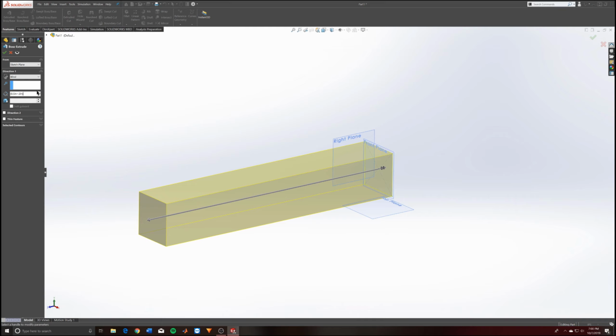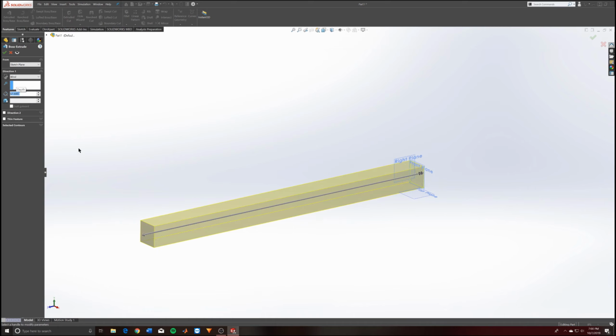You can mess around. Here, hold on, let me see. I'm just going to do 5 feet minus, yeah, and there you go. And it doesn't even need to be the same dimension type. Just make sure that you put the standardized dimension tag with it. So if it was inches, you put IN, or if it was millimeters, you put MM, or meters, you put M, etc.